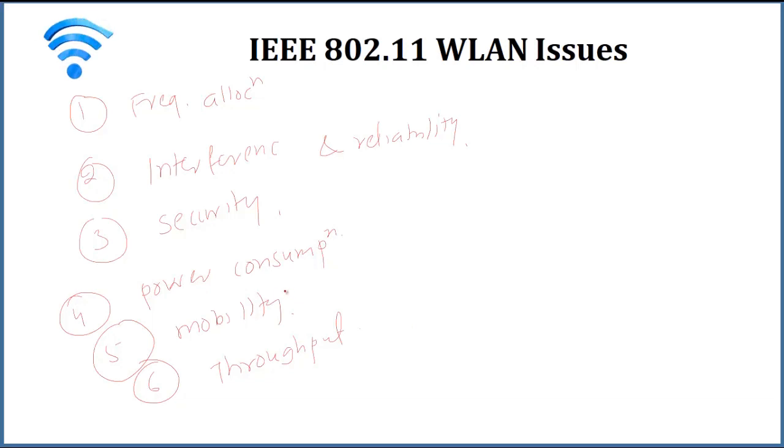Now you have used this thing as an advantage, so what is the issue? All users must operate in a common frequency band. Then the frequency band must be approved in each country, because if 2.4 gigahertz is being used in some other countries, and in your country the spectrum allocation agency says that this is not allowed, then again there will be a problem of manufacturing those kinds of devices, since the Wi-Fi used in the US is not being used in your country. So that kind of flaw will be there. So you will need to operate all the users at a common frequency band.